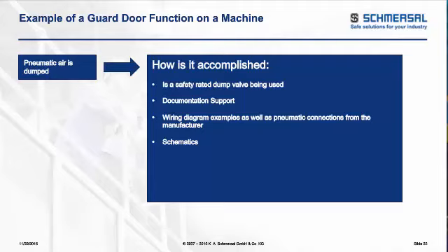Are you not only wiring them up, but piping them up properly? Some examples: a manufacturer may supply the muffler built in so you don't restrict airflow, while other manufacturers may recommend a certain size muffler that you have to add on to the safety valve so you don't restrict airflow.